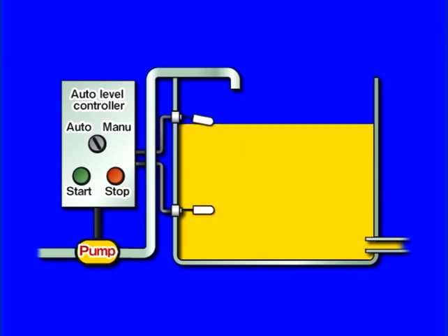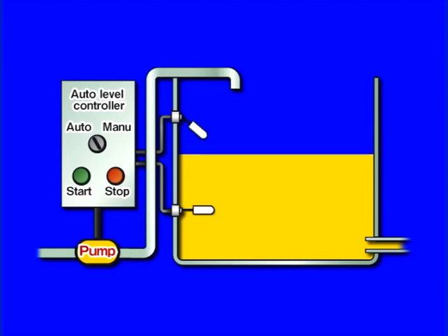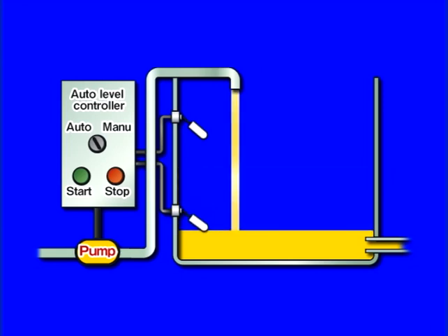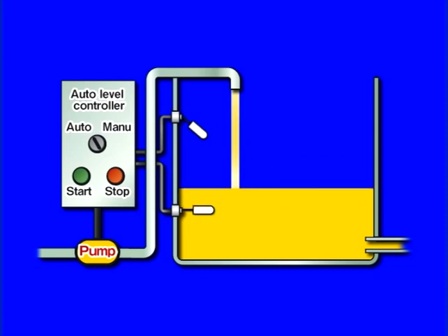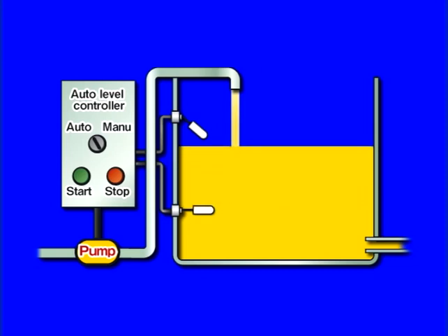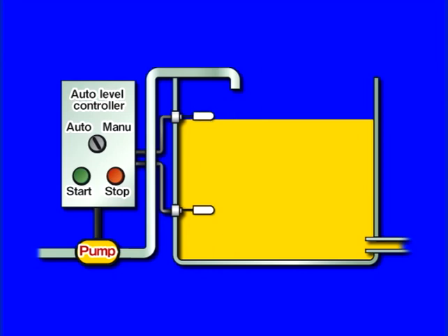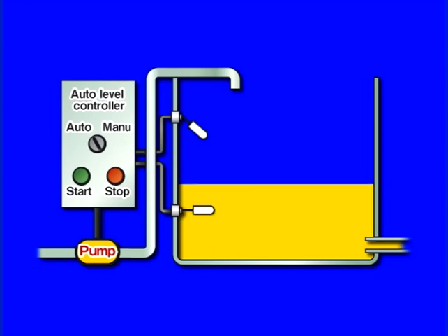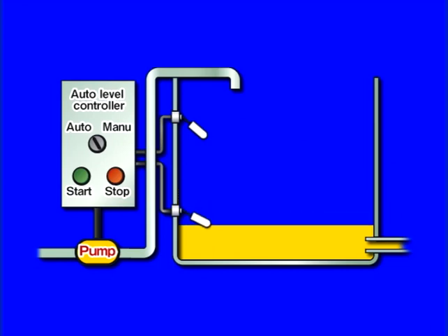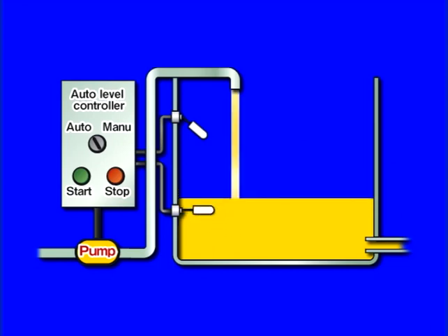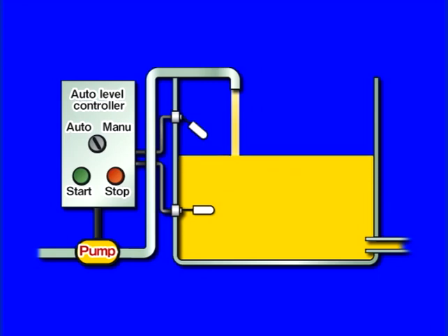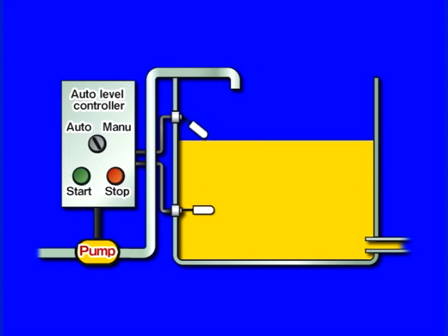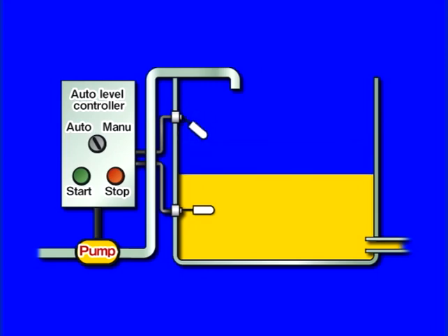The motor that supplies power to the pump generates a modest amount of heat while operating. However, when the motor has been stopped, its temperature gradually begins to decrease. If the motor's temperature becomes cooler than the ambient temperature, condensation on the casing and coil could result. Condensation inside the motor can result in overcurrent, an event that takes place when insulation resistance between the coils decreases, leading to a short circuit. Reduced insulation resistance between the coil, motor, and the motor frame can also lead to electrical leakage.